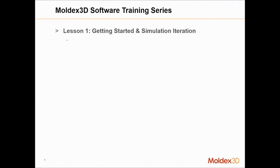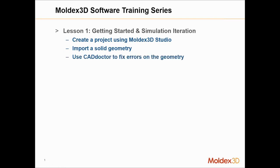So in this lesson, we have created a project using Moldex3D Studio. We've imported a solid geometry into CADdoctor, and we learned how to use CADdoctor to fix those errors on the geometry. Coming back into Moldex3D, we selected a gate location, and then we used an iterative process to determine whether that gate location was appropriate, and learned how flow balance will impact the final results that we get out of the simulation.